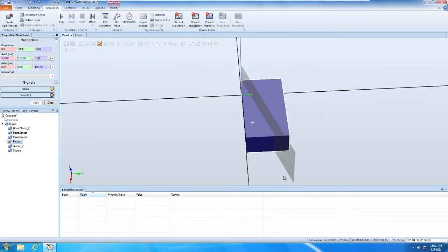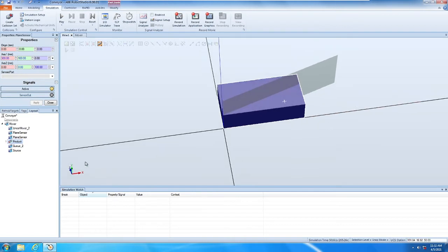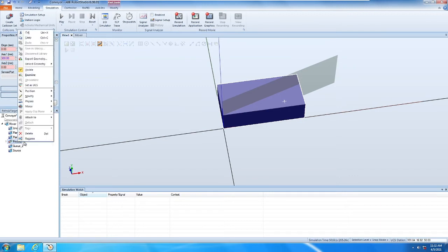So that means this gap here to there, the minimum distance between two products is this much, from this corner to there. This is the minimum gap between the two parts. Okay, the sensor is good. I'm happy. And then this one, what you need to do is...